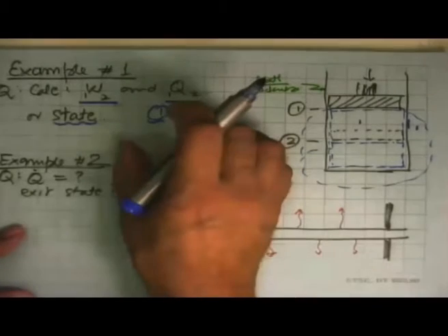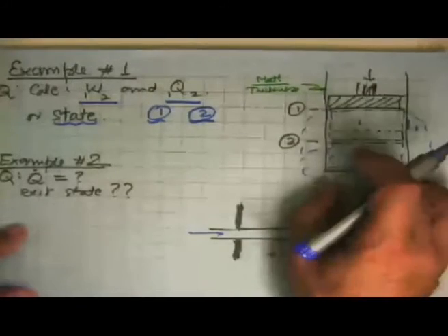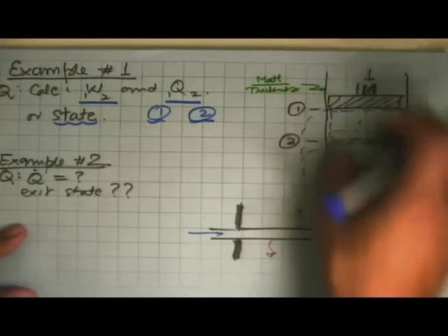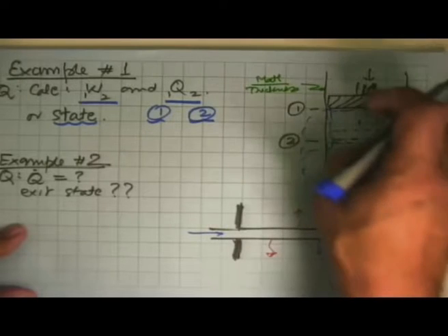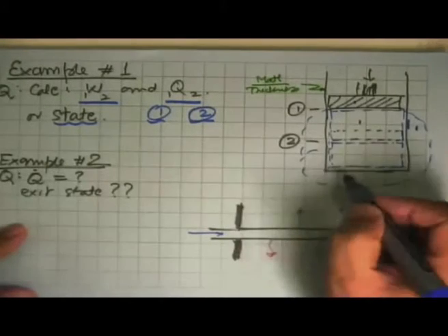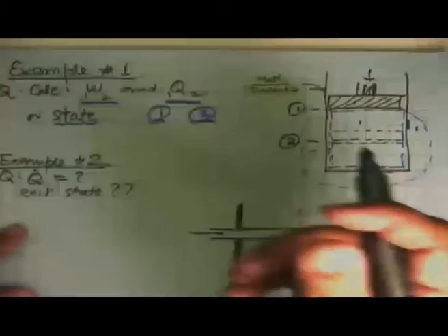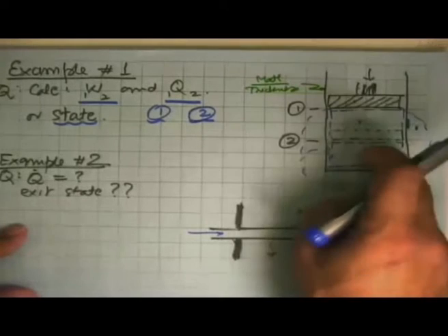And this information is important, because from this we start doing the engineering of this device. For example, if in this process we know that this is the maximum pressure that the substance will take, we know what we can then design: what material should we have here, what material should be there for the cylinder, how thick should it be, how it should be made. All those decisions get taken based on these thermodynamic considerations.